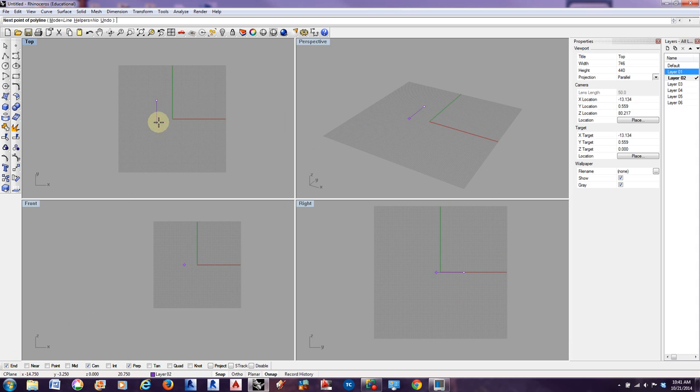If you hold the shift key down, it kind of locks it. So I'm in the top view, and you'll notice that in the right, in the front view, all we see is a dot because we're drawing that line in a view. Basically, in the front view, you can't see that, right? Because it's just a straight line. And so as you're looking at it in the front view, it's just a point in space, right? So similar to the right view, we're looking at this now.